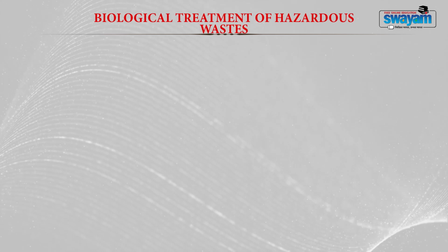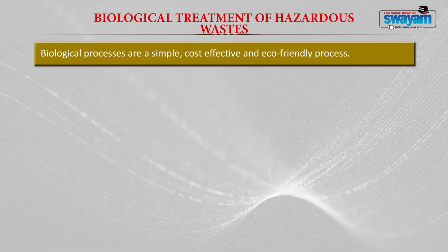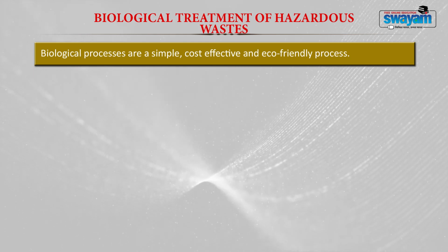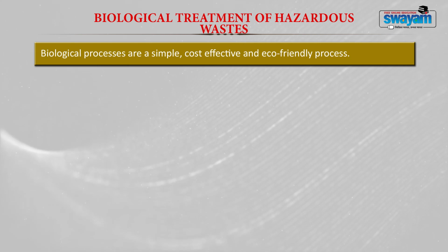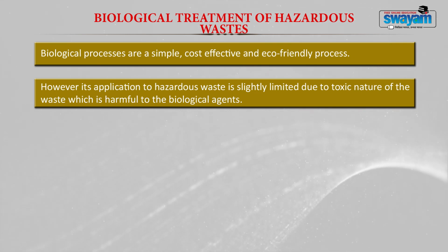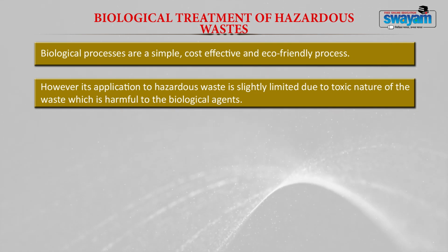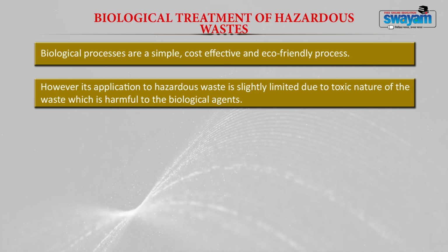Now, let us look into the various biological treatment methods. The biological processes are generally used because they are eco-friendly, cost effective and simple in nature. Their application to hazardous waste is generally limited because these hazardous wastes are toxic to the biological agents involved, like bacteria, fungi, actinomycetes and so on.